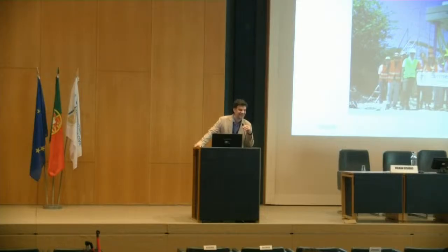Sure, thank you. My question is about the soil nonlinearity. The idea of the dynamic impedance function is based on linear elastic soil domain behavior. Is your dynamic impedance function different if you apply a different force at the same frequency? I'm sorry, but I didn't understand.